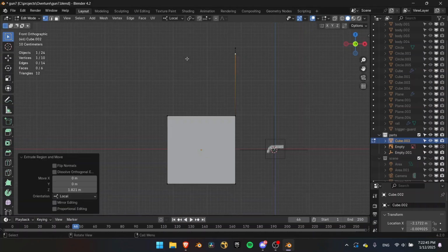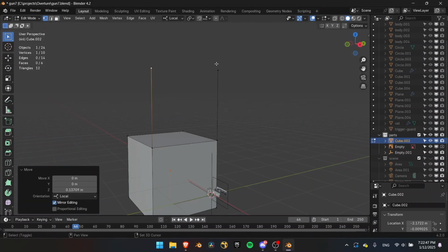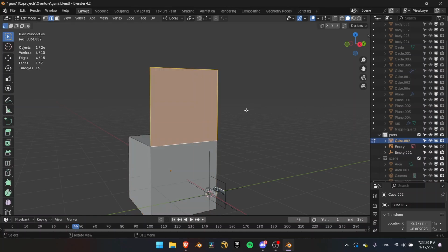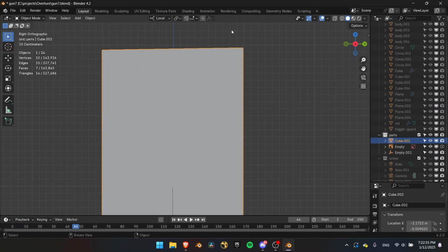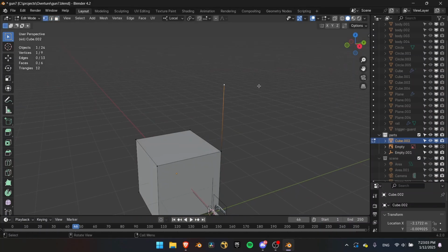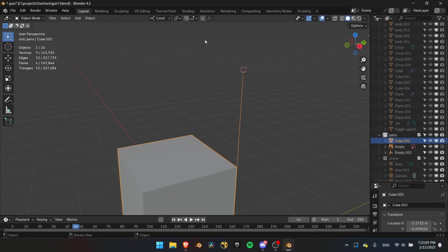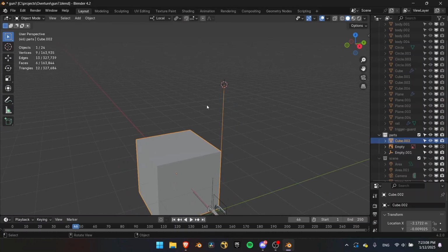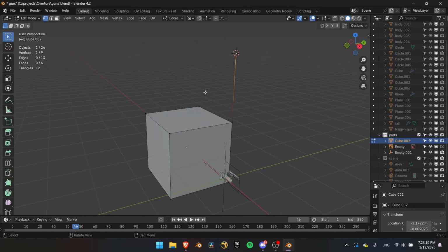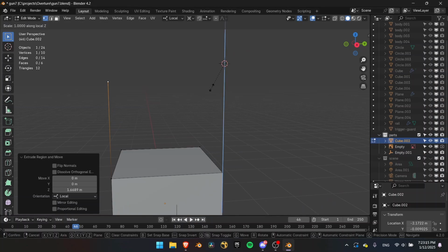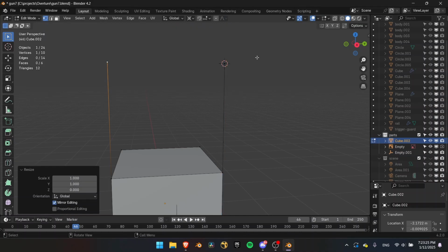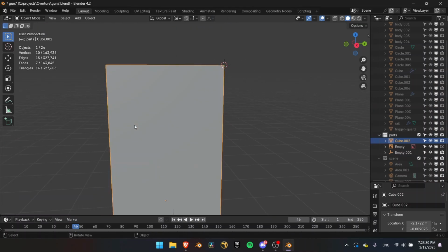You'd think, oh, I think this is right, and then do this and merge it, and then it's like, oh, you have a square, but it's really not a square. You can tell that it's not a straight line. A way he does it is he puts the cursor to selected right there. Let's change this to not individual origins. What do I do? 3D cursor up. Extrude it out, right? It's clearly not a line, but you can just scale it along the z-axis and put to 0, and it automatically aligns it to this point right here, and then you have a perfect square like that.